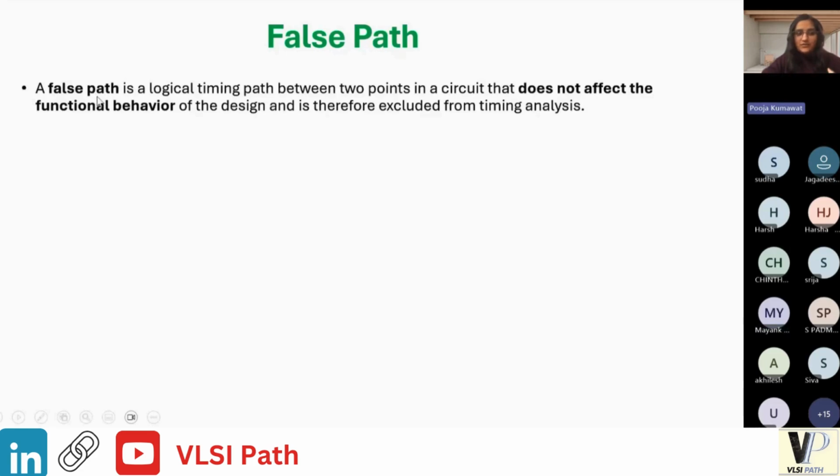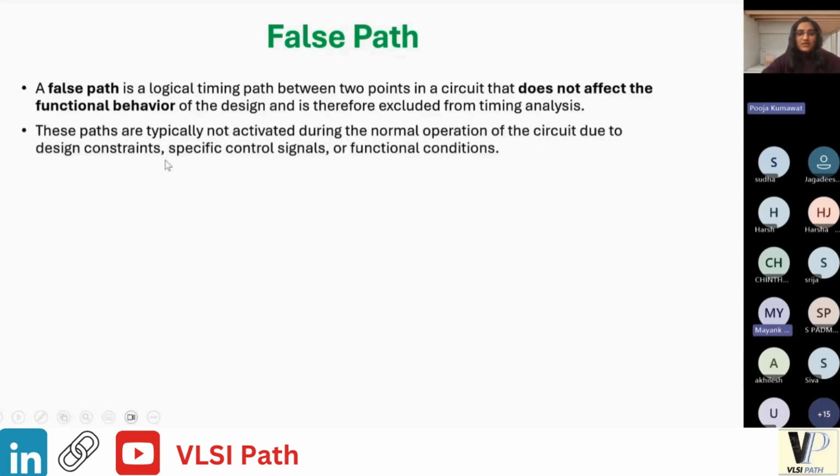You can see a false path is a logical timing path between 2 points in a circuit that doesn't affect the functional behavior of the design and is therefore excluded from timing analysis. Meaning, functionality-wise, the path which our design will never take is what we call the false path. And these are not activated during the normal operation of the circuit due to a specific control signal or design constraint.